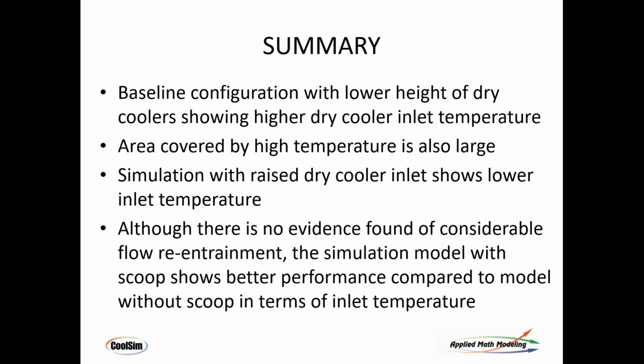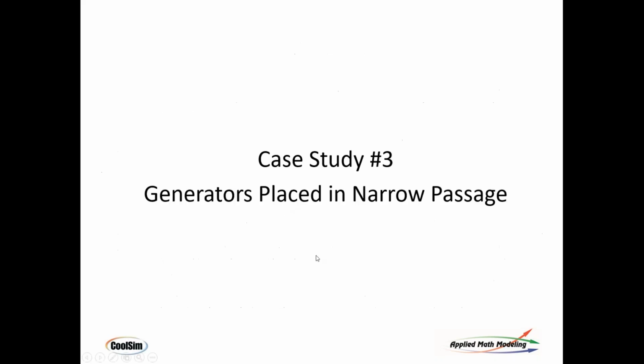There wasn't any reentrainment. We ruled that out fairly quickly, but we did notice the scoops help because you've got buoyancy, you've got velocity. When you have a temperature delta like that, the stack effect can be positive in your favor, and that's what we found in this case.